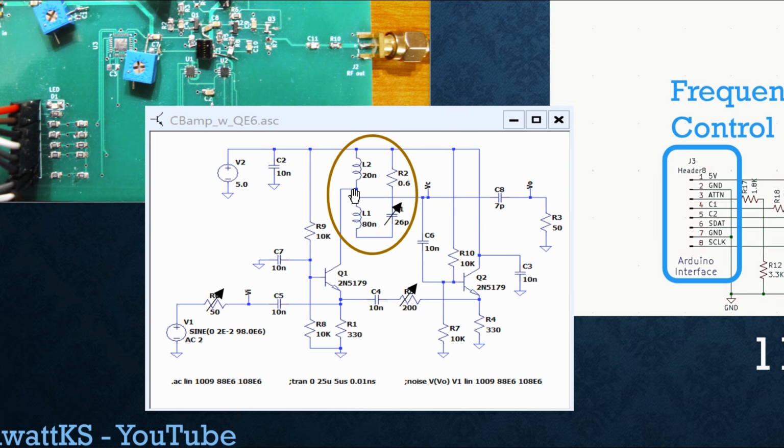So why? What are we doing? Well, remember the gain of this device is GM times R, where R is whatever you see looking out the collector. So 250 ohms here. There is some loading, but I made the loading light, so just think about it being 250 ohms.